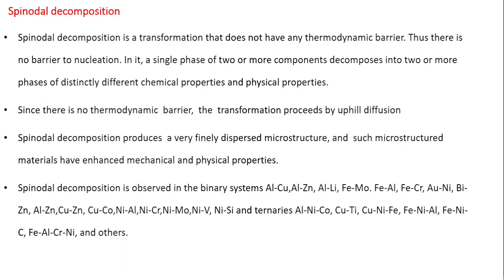Now let us talk about the spinodal decomposition proper. The spinodal decomposition is a transformation that does not have any thermodynamic barrier. Thus there is no barrier to nucleation either. In it, a single phase of two or more components decomposes into two or more phases of distinctly different chemical properties.